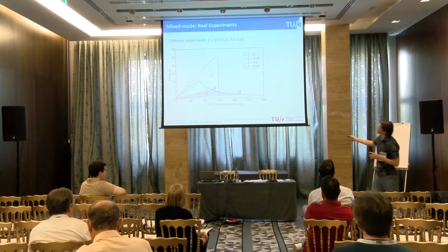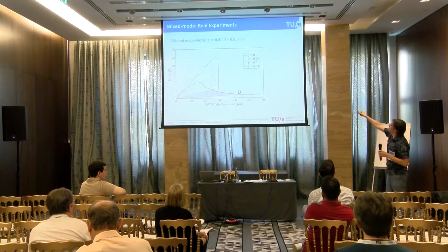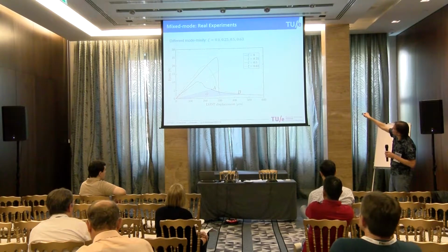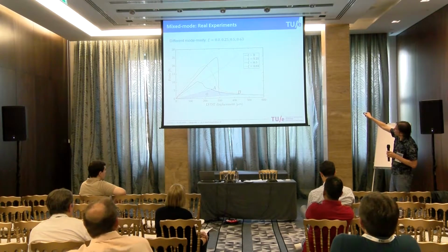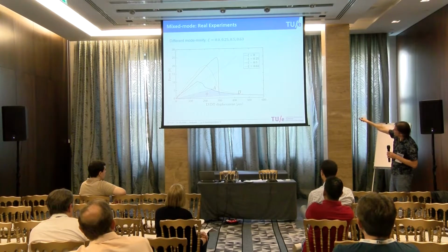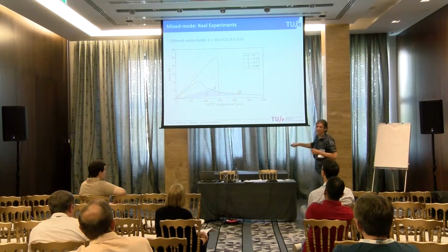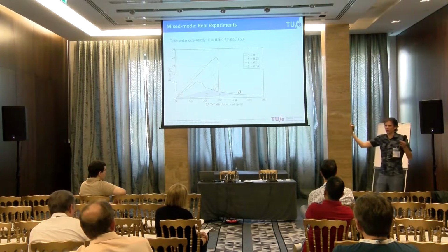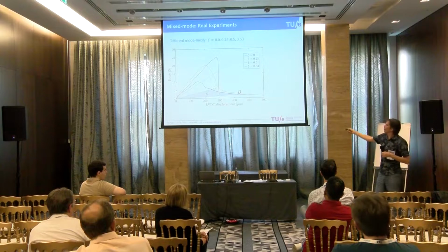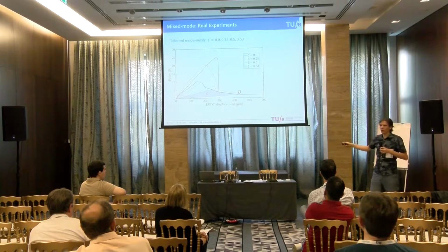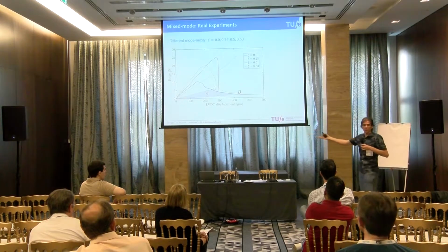Now, finally, almost to the end, the real experiments. We did these real force displacement curves here. You can see that already at this mode mixity parameter of 0.63 there's basically catastrophic failure, so it shoots through the image. So there's no information there. The 0.5 is like this, but you can already see it becomes a bit unstable. So it's not as good as we predicted numerically.